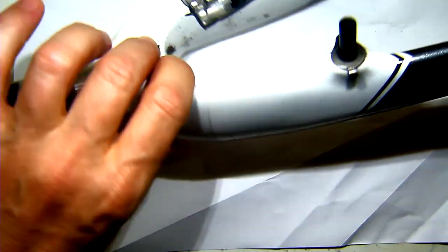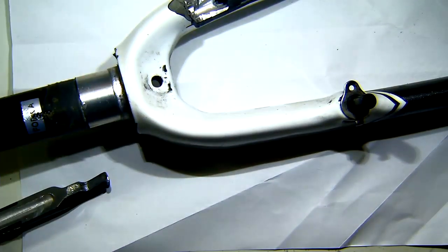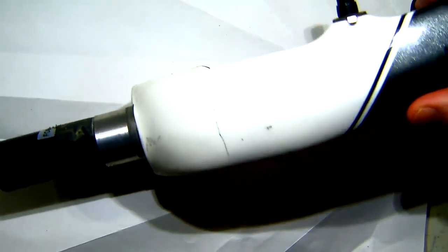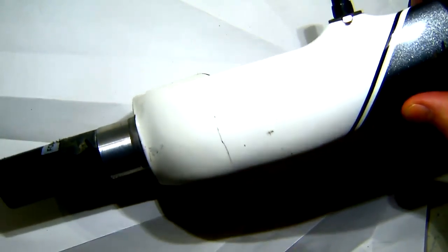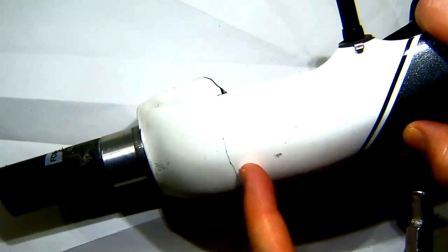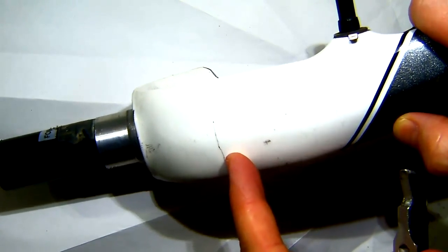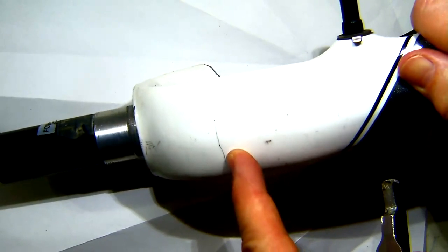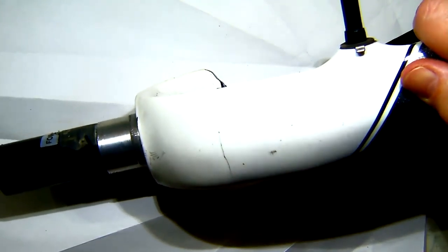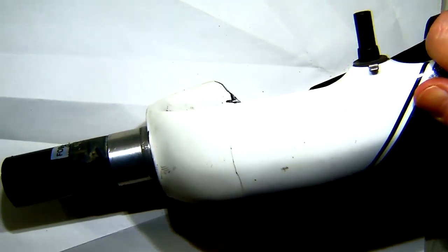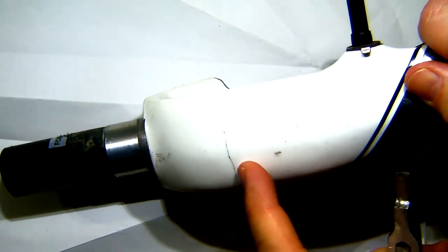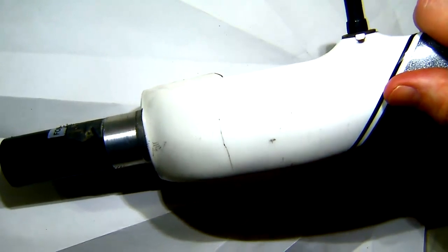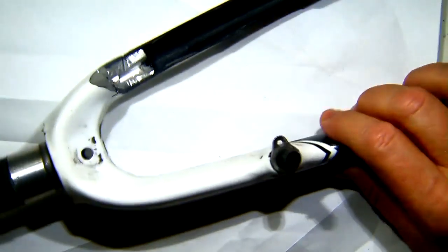And for those people who've got fancy whole frame carbon fibre bikes, thinking, oh, yeah, that'll be great, that'll last me a long time, don't be so confident. First crack is the end of the frame. We're not talking about yield strength going to ultimate tensile strength, and you've got a long elastoplastic zone, as with steel. Once this has happened, we can't trust it anymore. This could just pop off at any time, just like that little cracking sound you heard just then. It's got to be replaced.